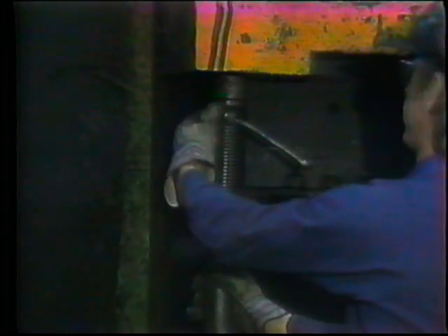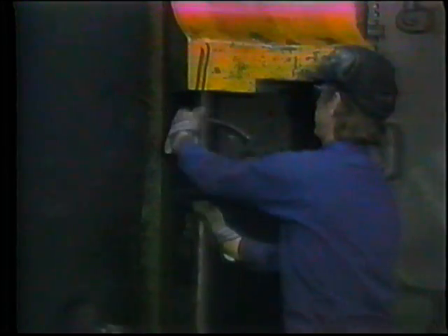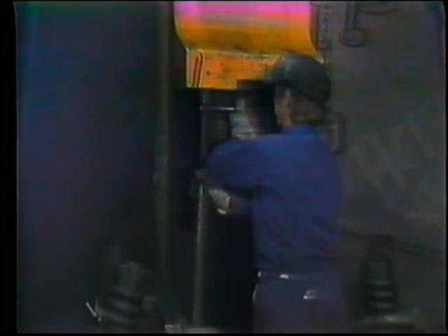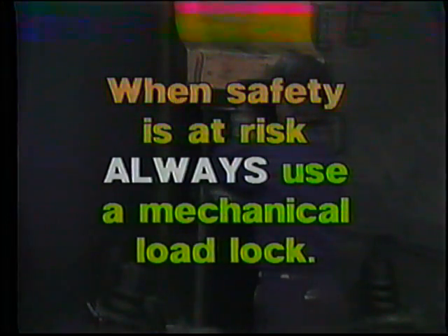It's never a good idea, however, to rely on any one component, such as a check valve, to keep a load locked in place. Hydraulic systems can and sometimes do fail. If safety is at risk, always use a mechanical load lock to keep the load in place.